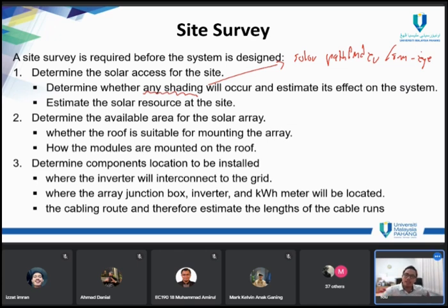Basically on the design, maybe you write 20 meters, but if you get to that building, maybe there's some reason like a curvy angle, or there's some slab, so maybe you need to change the route of the cabling. That's why it's very important to do the site survey, to go there and know the real situation of the physical structure of the building. In the picture maybe it's okay and you just decide how many meters. But if you go there, you may need another cable route, because there's a fan there, for example.